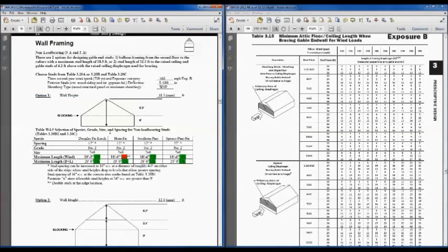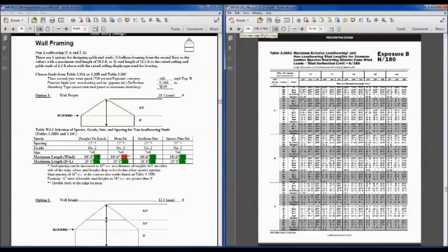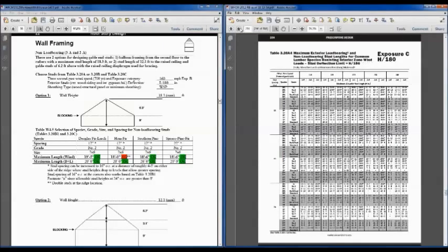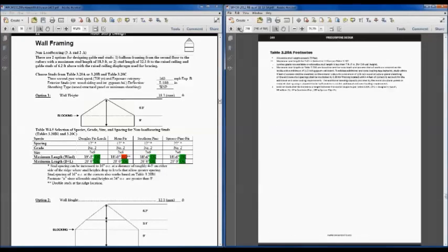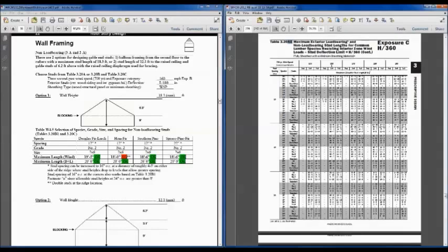Tables 320B, and let's do some design with the stud tables. So let me get there, and then let's jump to Table 320B1, and I'll tell you in a second the difference between 320B1 and the 320A tables. So before I leave 320A6, I'll just point out to you that these tables are for studs that are fully sheathed with what we call minimum sheathing material. That could be foam sheathing or some sort of minimum sheathing material that does not give you the composite action that a wood structural panel will give you. So that's the distinction between the tables with the A designation